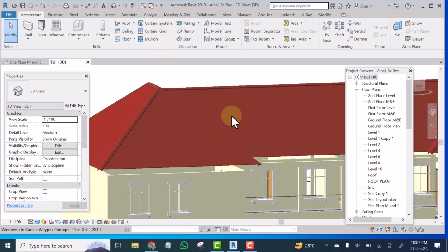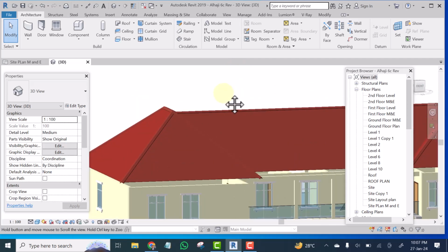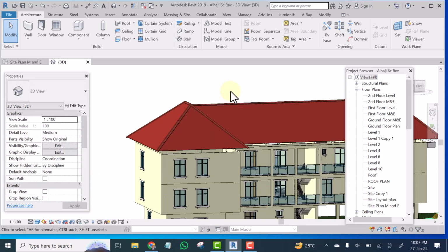So this is my Revit now. If, for instance, I want to model a concrete fascia, for me to be able to sketch the outline of the sweep, I will need to be on the floor plan. So in sketching out the outline, you are either on the floor plan or on elevation.